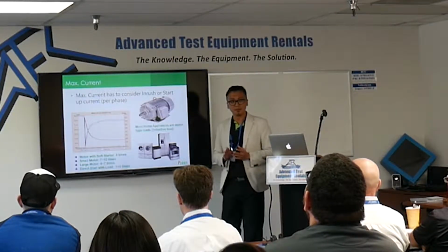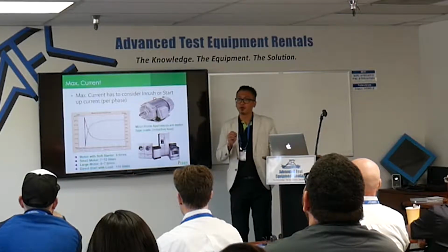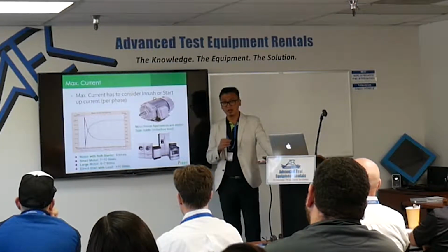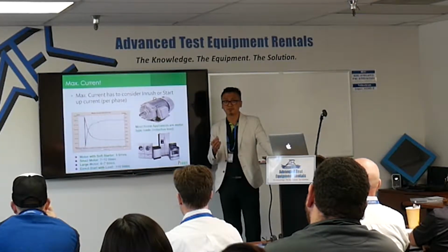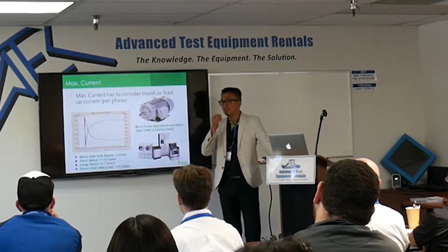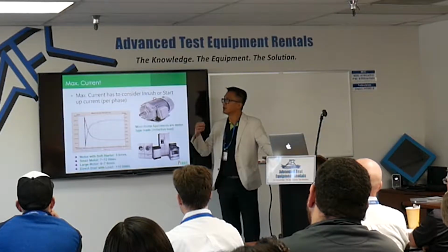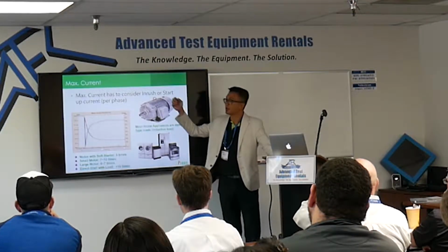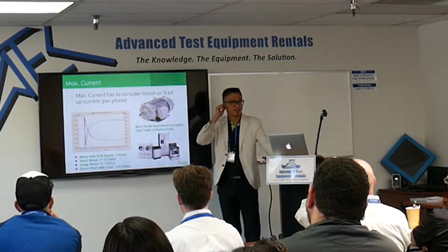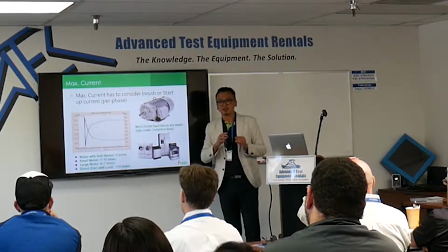The next one will be very critical for us when we help you select the right kVA power supply, because most customers do not realize the importance of the inrush current.